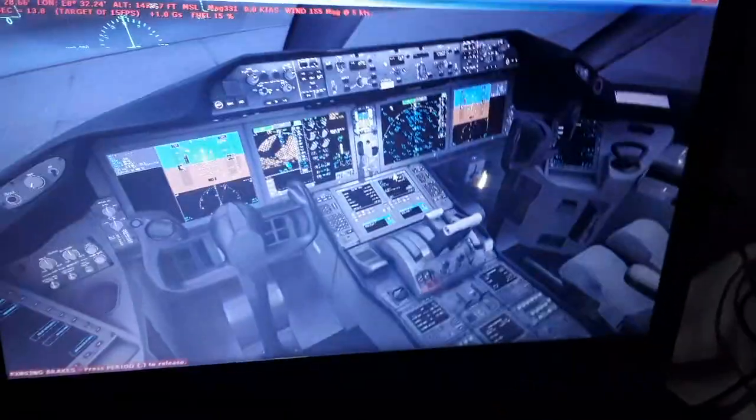Also the outside view. So you will see how I control them using the side stick to control the elevator for climb and descent, the ailerons and the spoilers, using the control wheel to make banks left and right, and also the rudder pedals for yaw turns using the rudder, and also for nose steering using the tiller on the ground, and also for toe brakes. So we have many controls in the rudder pedals. We have also the elevator control, the horizontal stabilizer trim function of the elevator, the manual trim switch over here, and here the alternate channel.